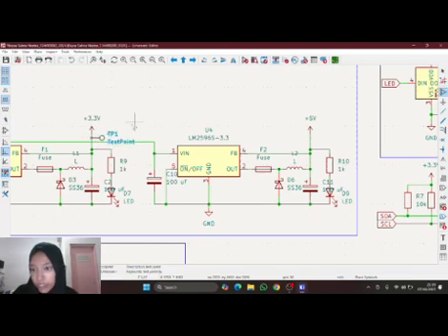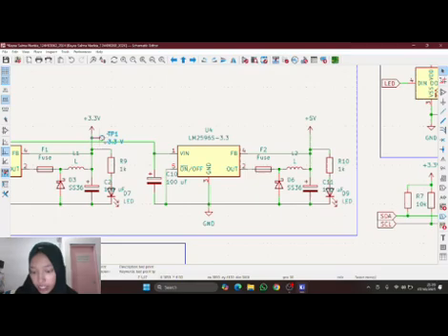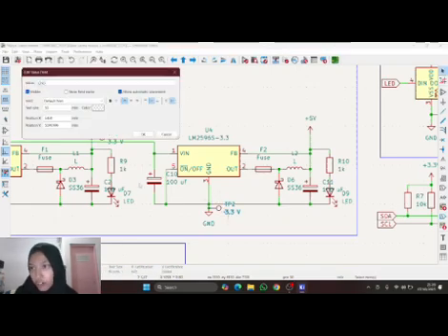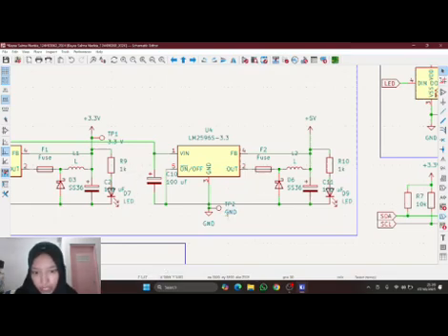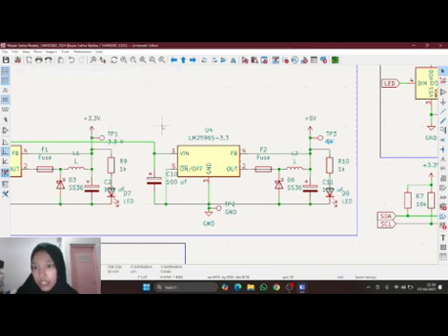We can put it right here, and then you can change the test point name to the name of the volt power. Like this is 3.3 volt, so just rename that, and then you can do the same for the other two. I'm gonna add it here for the ground and then rename it as GND or ground. Okay, and then duplicate it again using Control D to place it in the 5 volt and then change its value to 5 volt, then clicking OK.